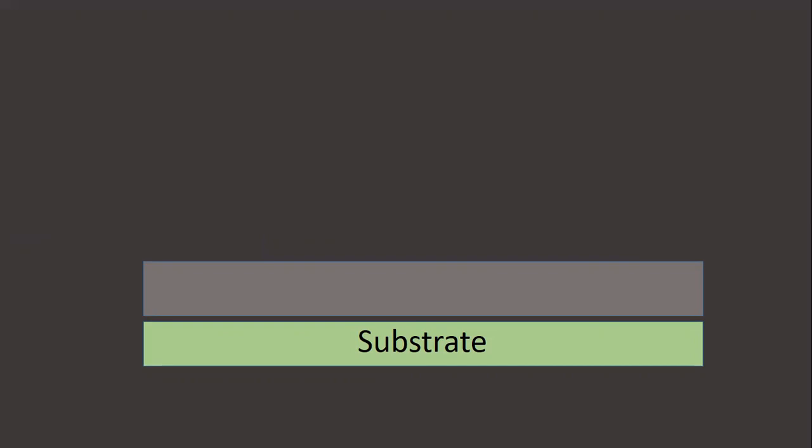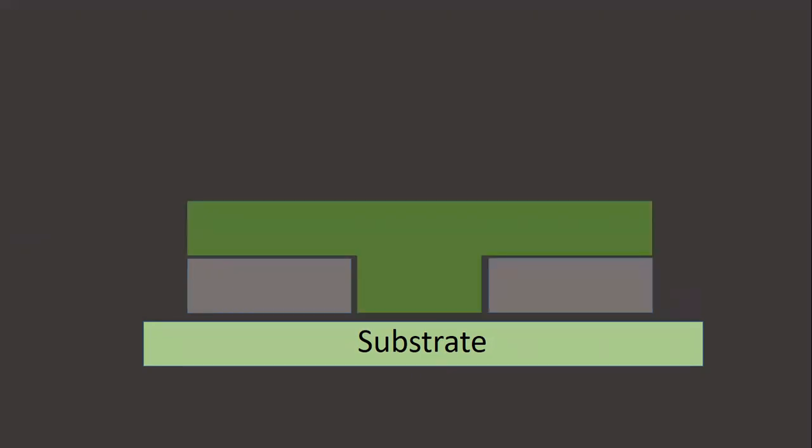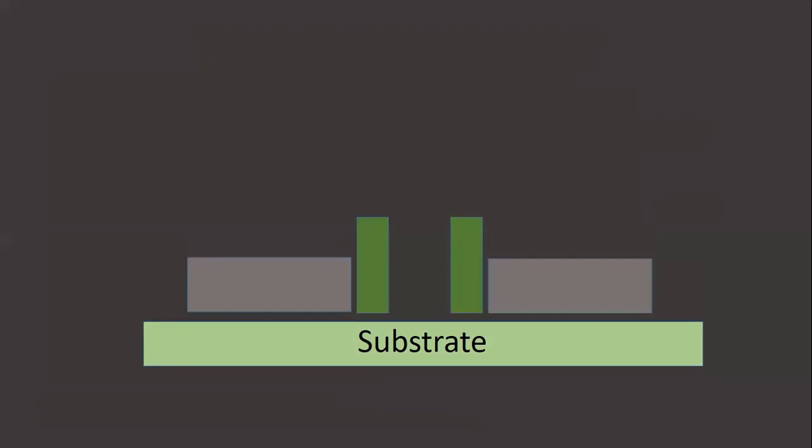But what we can do with thin films is that we can use other subtractive processes like chemical etching to pattern these into simple geometric shapes. So now we're kind of getting somewhere. We've patterned our first material. So now we can deposit another material on top of that, again, probably from the gas phase. But since this material is different, we can etch it away using a different chemical that won't harm our first layer underneath. So we can pattern it into something different.